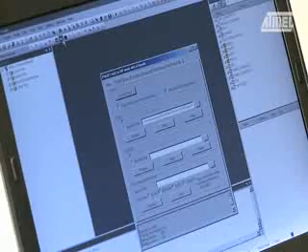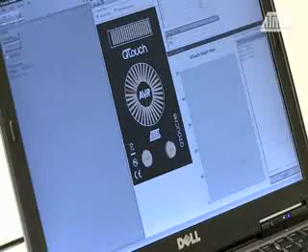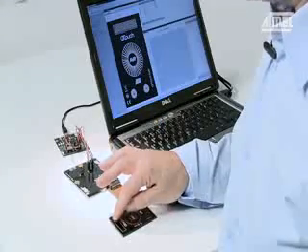With the QT600 kit connected to your computer, open the Connect dialog to program the target chip. Now our slider is ready. All the necessary algorithms are included, the I/O is set up and ready to go. But we won't be able to actually see anything happen yet. This is where QTouch Studio comes in. Launched from within AVR Studio, it provides visualization of your touch data so that you can see the slider actually works.